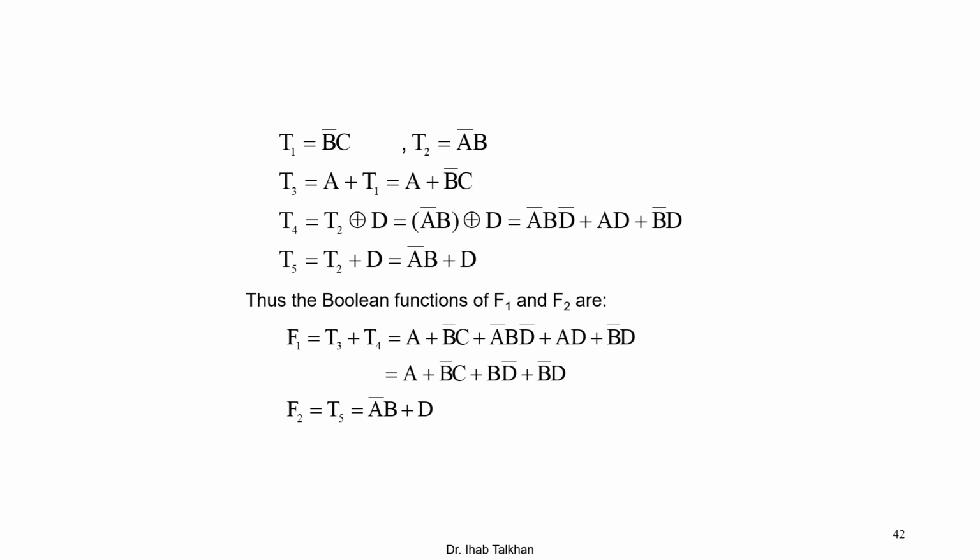So this is actually another way of solving a digital system, rather than giving you the idea and you go through it and find out the hardware. Here I'm giving you the hardware and you are labeling all the gates' outputs, and then you go forward from in to out to find the equation between F and the input variables, and then you can use the K-map in order to automate this. This is another way to solve a digital system, as shown here.